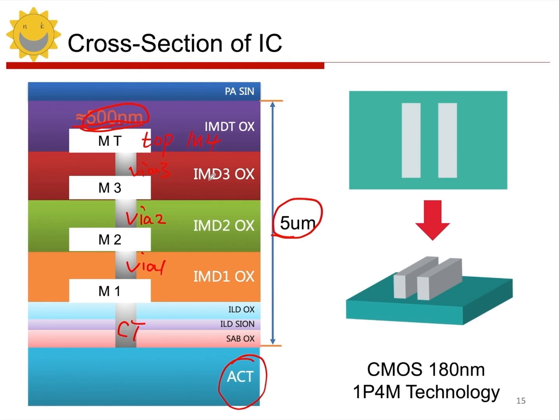Metal lines are separated by insulating materials, forming a capacitor. The capacitance size relates to the metal plate's area. The 0.5 micron thickness is significant, and long distances increase parasitic capacitance, affecting signals. We'll explain estimating this impact later. For now, understand that parasitic capacitance exists.